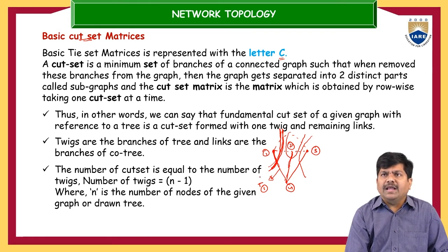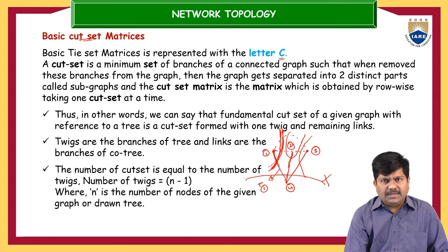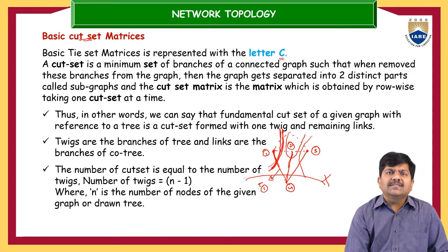Now, cutting can also be done like this. So, if you want to eliminate node number 4, and you are expecting a cutting like this, this is not a cut set. You can divide this graph in different ways, but a basic cut set means you have to divide the graph into two parts in order to isolate one of the bus nodes by cutting one of the twigs. Now, I want to isolate this node number 1 by cutting this twig.